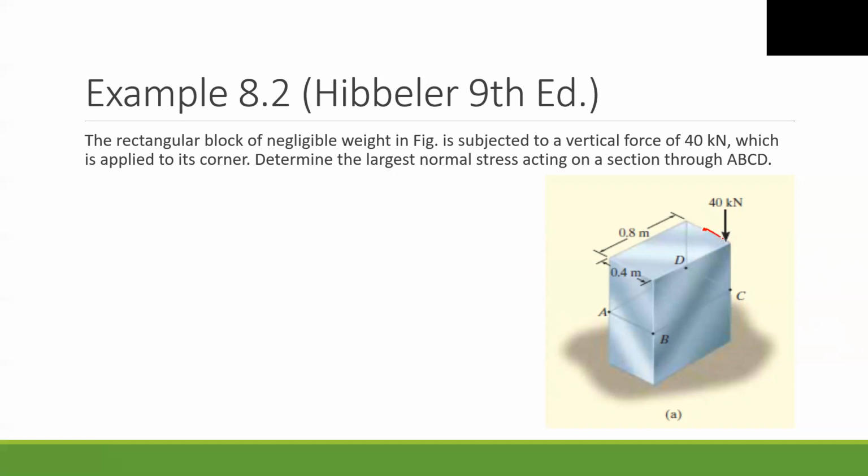The first is like this. I don't know the x, for example, this is x. Also, there is one more eccentricity, y, here. Therefore, if I want to move the load to the center of the section, we have two moments, moment x and moment y. Therefore, it is a little bit different. Biaxial bending occurs, in other words, in this question.